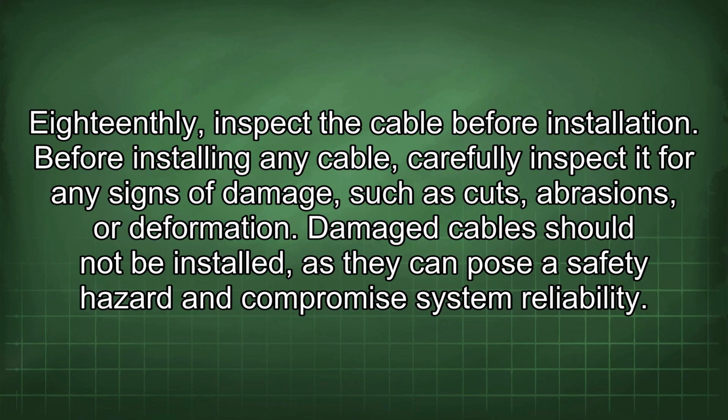18thly, inspect the cable before installation. Before installing any cable, carefully inspect it for any signs of damage, such as cuts, abrasions, or deformation. Damaged cables should not be installed, as they can pose a safety hazard and compromise system reliability.